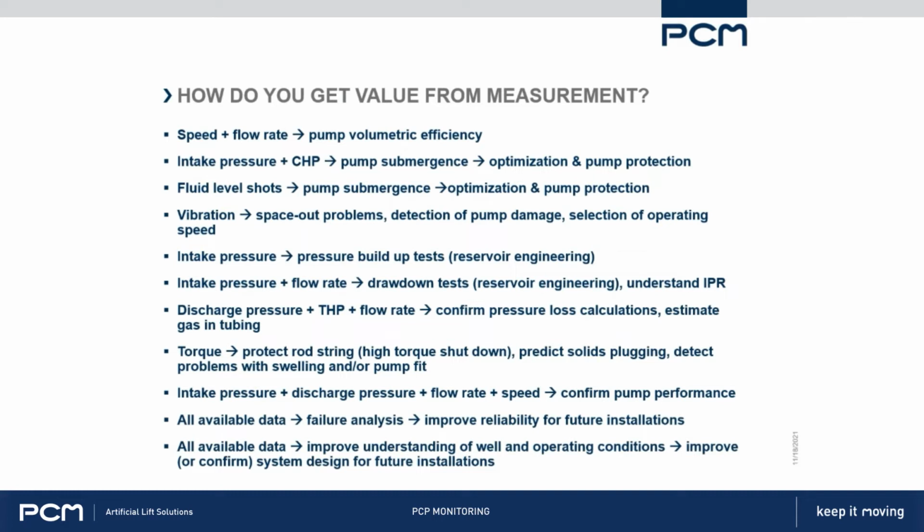If I have torque measurements, I can use that to protect the rod string and shut down if there's high torque. I can also use that in some solids applications to determine whether I need to call out a flush by, to prevent the well from going down.